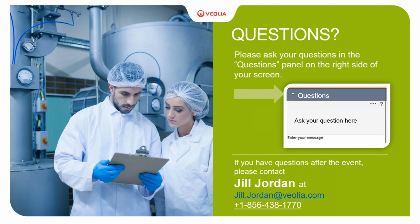Okay, so everybody wants to know this. And again, if you don't want to pay that much, don't charge that much. Some people want to give it away because they don't want to pay to have it taken away. And that's obviously the lower range. The upper range, I think, is about 65 to 75 cents a gallon. And we assume that gallon is at least 60,000 milligrams of VSS per liter. So we try to pay less for less concentrated sludge because I don't want to pay for transporting water.